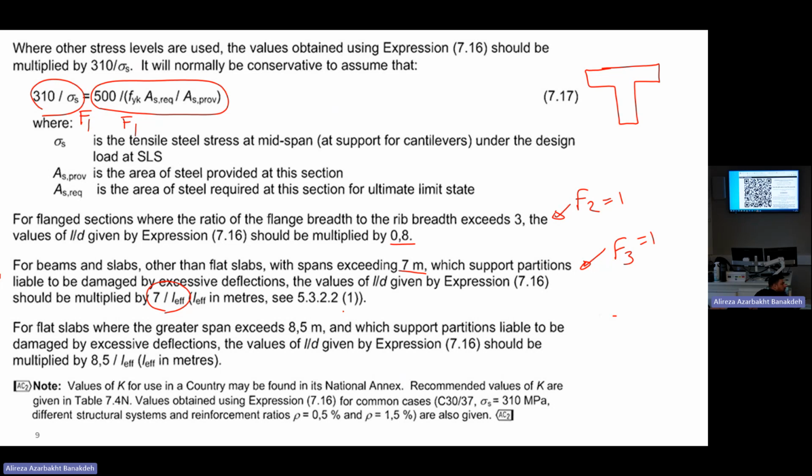You know, you're engineers. If there is a question in practice and the edge of the support is provided, you use it. Otherwise, if it's not known, think: okay, this is a structure, I assume something for that. In design, everything is not clear. You say, probably I will have columns of 40 centimeters, or walls of 40 centimeters, so 20 centimeters and 20 centimeters should be deducted.